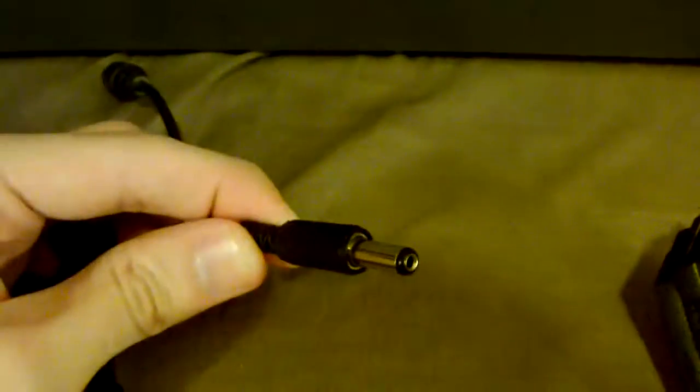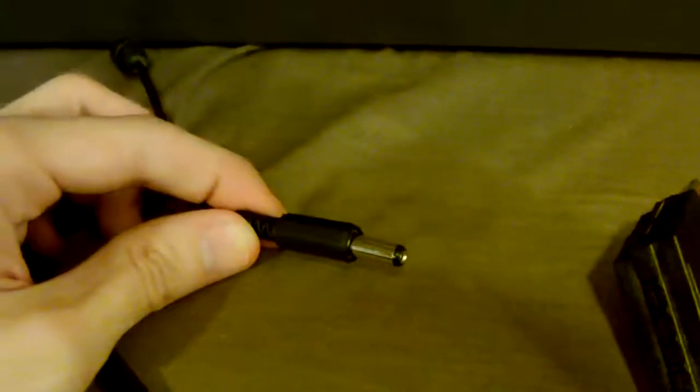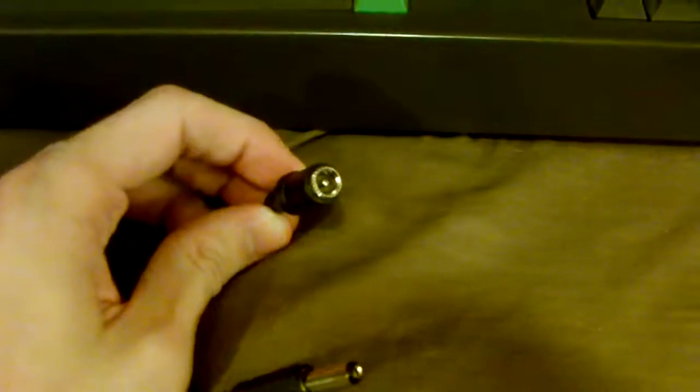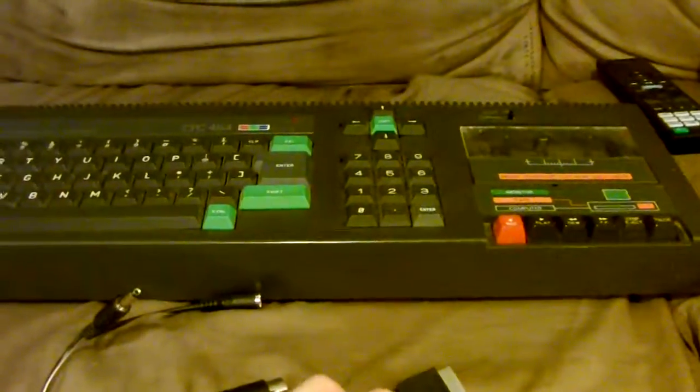Now the other weird stuff coming out of this cable right here is that right there, which of course plugs into the power on the back. That is a standard barrel connector for DC power used on many things. And then into that right there is the reverse of that connector, which is what you plug the AC adapter into. And the AC adapter that I have for this, which I didn't set aside because there's nothing special about it, is an ordinary 5-volt DC power adapter. So you plug the power into there, plug that into the computer, plug this into the computer, and plug that into something that supports SCART, and there you go. You don't need the special monitor anymore. So how nice is that, huh?